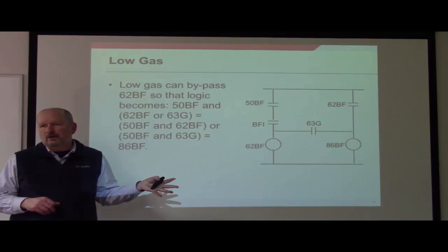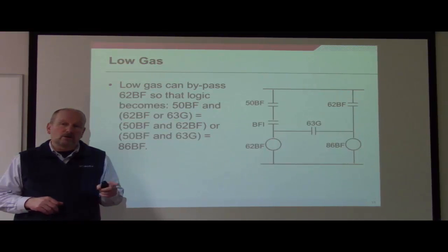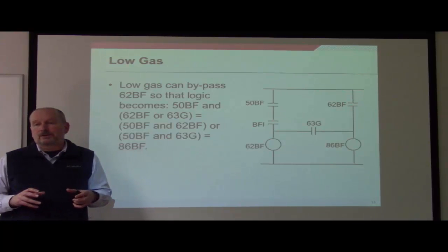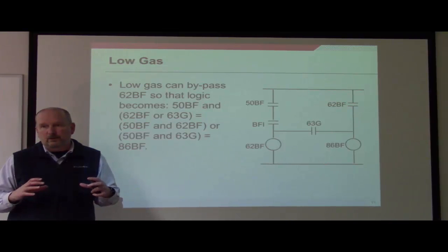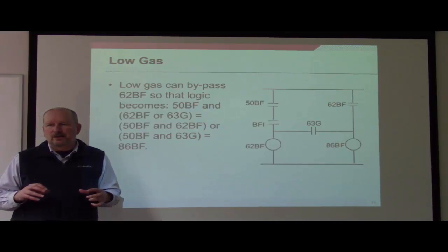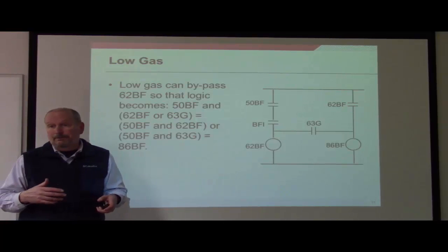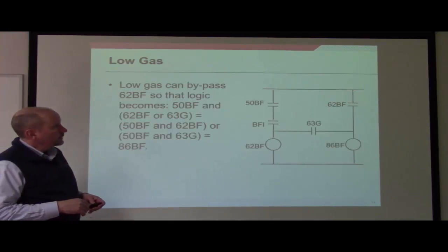So obviously you're not going to allow the breaker to close for low gas, but you're also not going to allow it to trip. Their concern is that if you have a trip, there'll be enough arcing inside of the cylinder that holds the interrupter that's going to increase your chances of having a flashover and actually damage the breaker. So anyway, they had that logic designed into their circuit breaker.